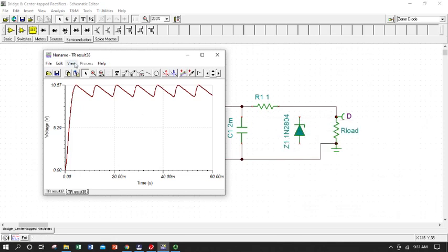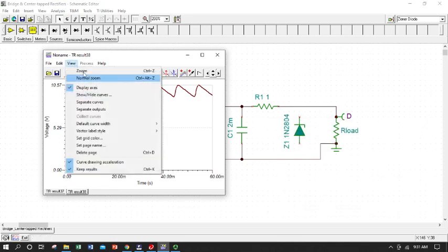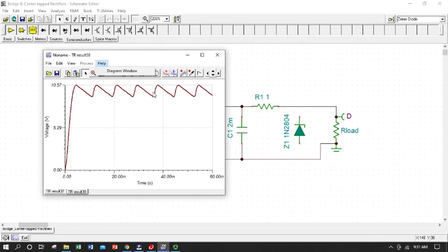We'll get a little warning because our Zener is not hooked up. And immediately we saw, as expected, the ripple increased, our variation, but let's see what happened to the average value. So we're going to set our measurement tool midway through the ripple, and we just dropped 1 volt out of 10. So by changing our load without realizing, we didn't change the setting on our power supply.